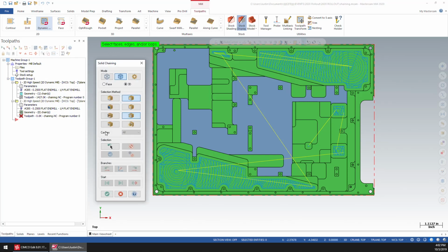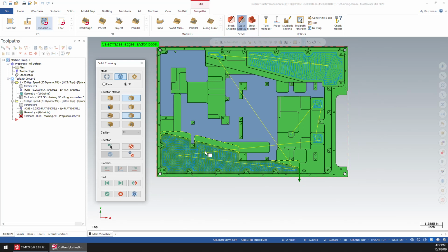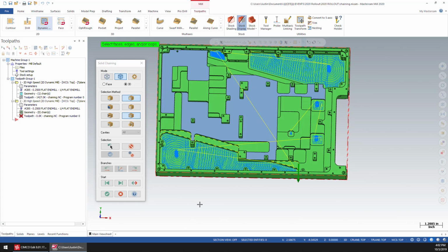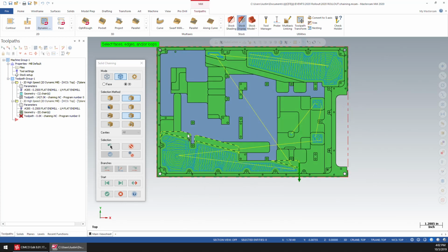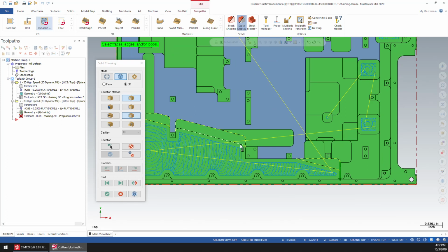So I'm going to go to my machining region, and I'm going to stay outer edges as well. And I'm going to pick this. Now here's the thing. You can pick as many open edges, like pockets that have open edges like what we have here, but you cannot have an air edge interfere with a containment edge. So my example to that would be these pockets here and this pocket and this pocket. I've defined this as a containment, and I'm going to define this edge as an air, but then this would be in containment, and part of my containment here is now set to air.